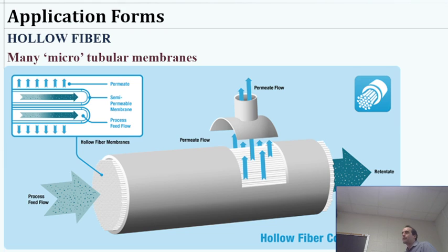So the question is, is this the most efficient? I would say it's for sure going to be the most efficient in terms of the surface area you get per chamber. In practice, it probably depends a little bit on how effective the backwashing is and stuff like that. Are there other considerations? But I think most applications that use something like microfiltration or ultrafiltration are probably using these, so that probably is overall most efficient. There may be some times where there's a reason to do something different.